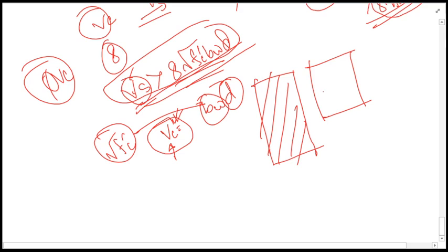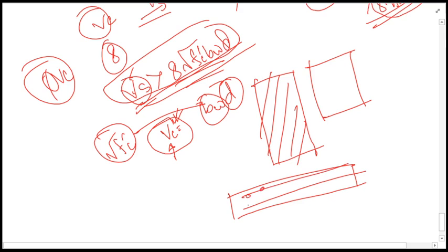So the number of 2D frames, that many shear reinforcement designs you will have got. And for 8 individual designs, you will have to provide 8 individual longitudinal sections, 8 individual sections with shear reinforcement like this.